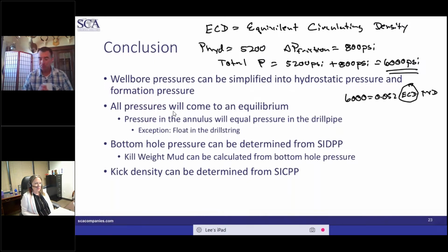How are the calculations made with underbalanced drilling? Depending on what the question is asking, I could go a couple of ways. I think they're probably talking about managed pressure drilling, in which case we're basically going to look at the formation pressure, and we're going to look at our hydrostatic pressure, and we'll be able to see how much underbalanced we are as the difference between the two.